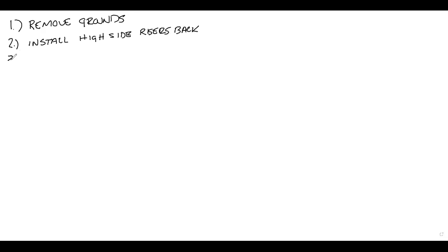Okay, 3. Now remember, through this process, we've had an open vacuum switch the whole time. So this is okay to do. We're not actually energizing the bank yet because we have an open vacuum switch. Close fuses, all 3 phases.